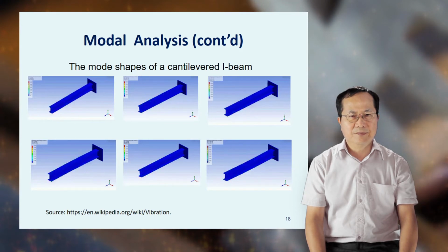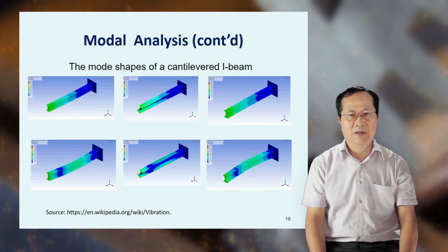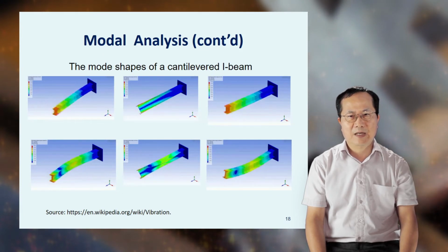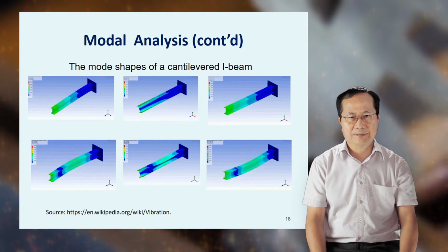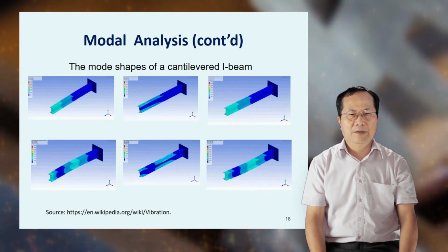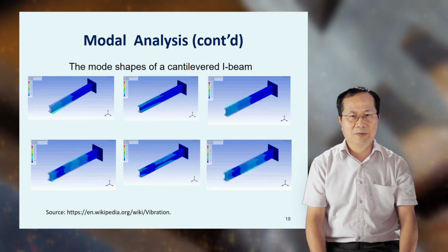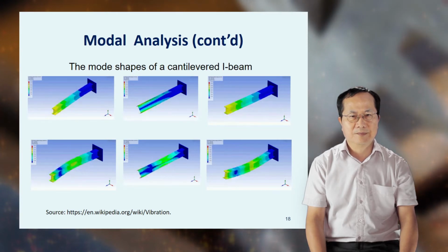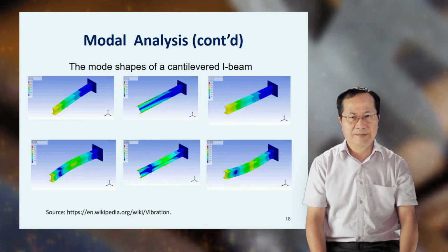In this case, the finite element method was used to generate an approximation of the mass and the stiffness matrices by meshing the object of interest in order to solve a discrete eigenvalue problem. Note that in this case, the finite element method provides an approximation of a meshed surface, for which there is an infinite number of vibration modes and frequencies.